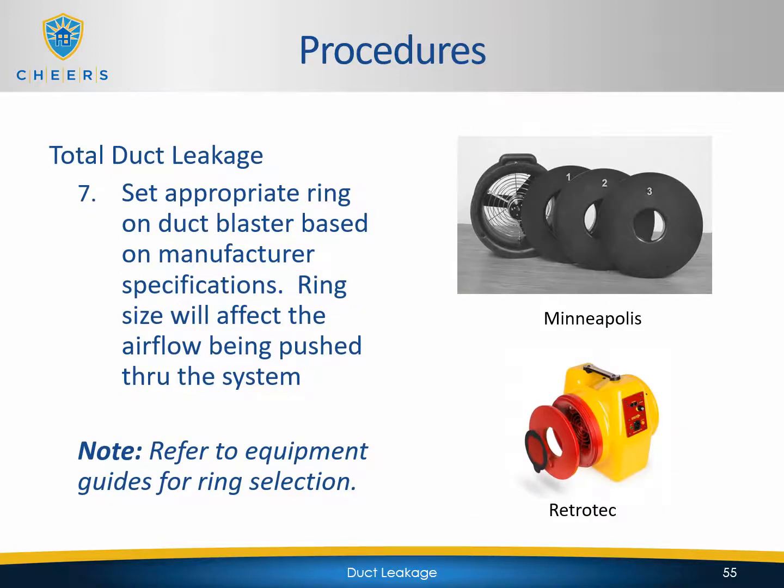You will go to your duct blaster and you will set the appropriate ring on the duct blaster based on the manufacturer's specifications. Ring size will affect the airflow being pushed through the system, and please refer to the equipment guides for ring selection. If you look in the back of the Cheers manual, the equipment guides will have information about ring selection, and again, once you actually do it hands-on in the field test, you'll get additional practice and